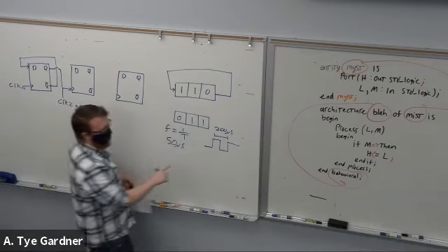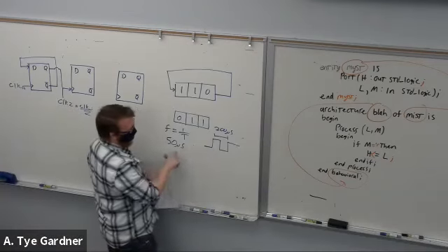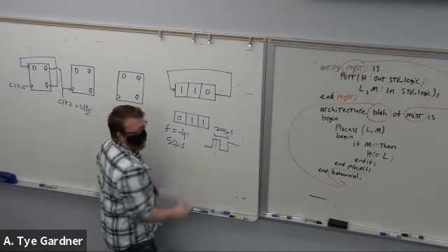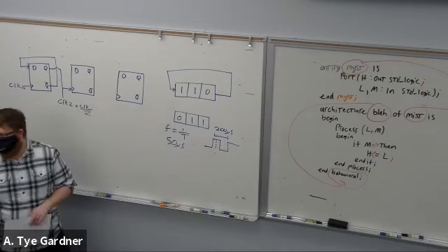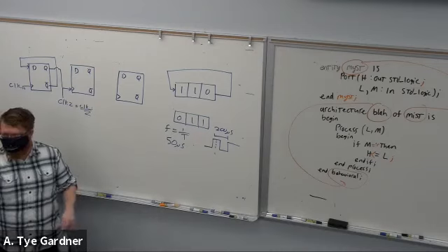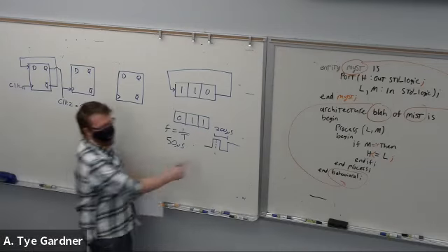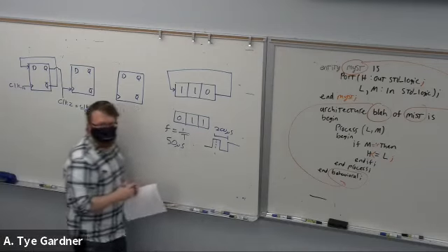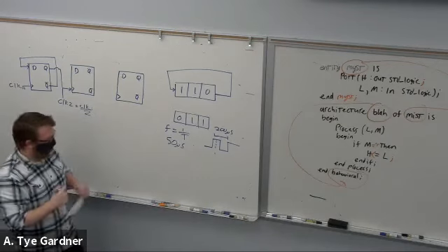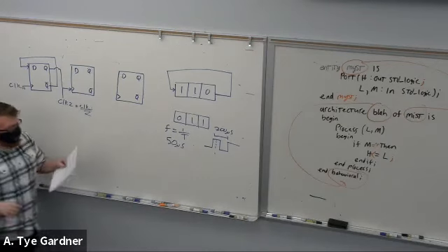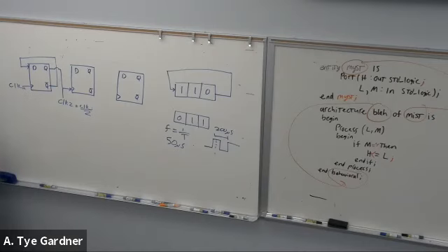So the clock to Q delay is a full 1/4 of that. Which then, if I have a 4-bit asynchronous one, starts to add up. That would be the harder version of that question. It turns out in the shift register, it doesn't actually break anything. It just kind of slows the ripple down.